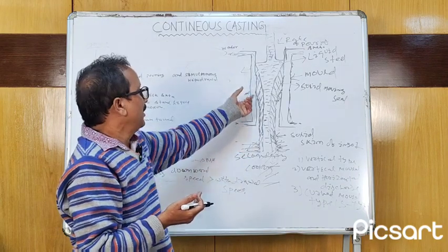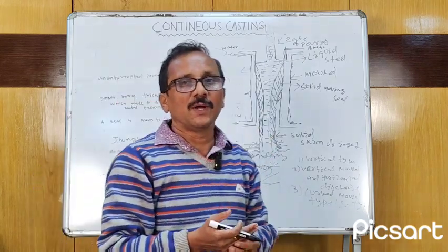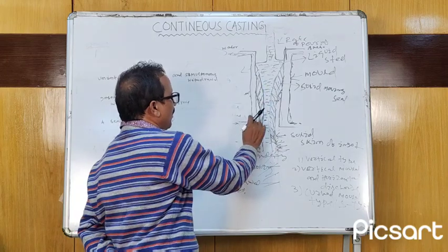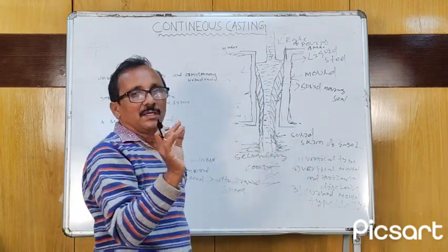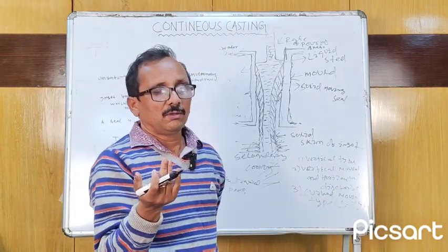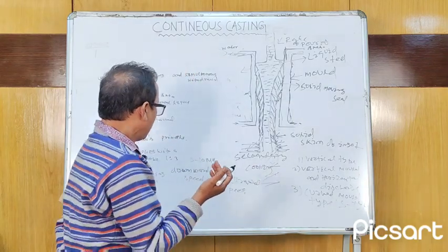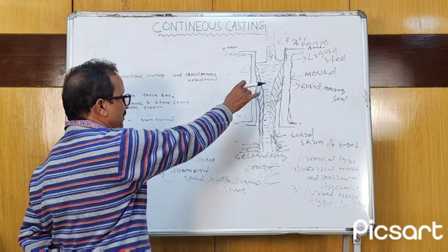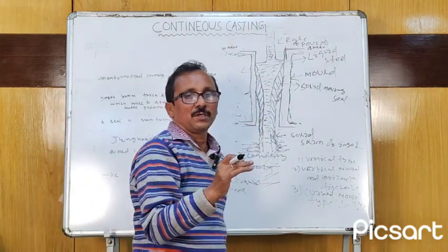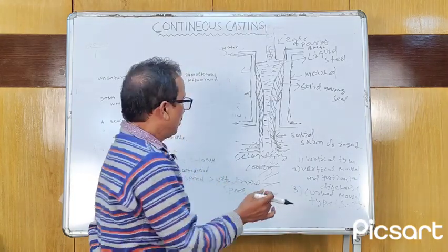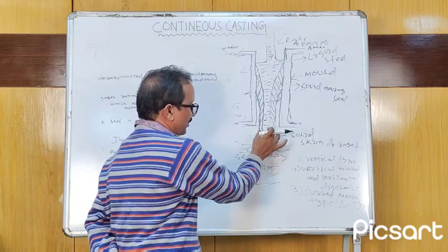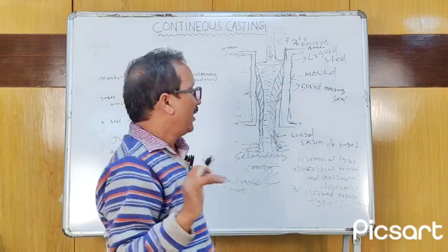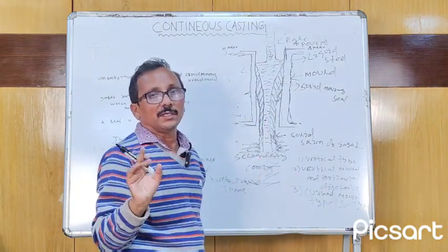For the stripping of the ingots, there is a principle in which the movement of the mold wall and the movement of the ingot are correlated to obtain good continuous casting without cracks. The mold stripping downward speed should be greater than the withdrawal speed, so that no transverse cracks occur in the ingot and we get a solid product without any defects. That is the main thing.